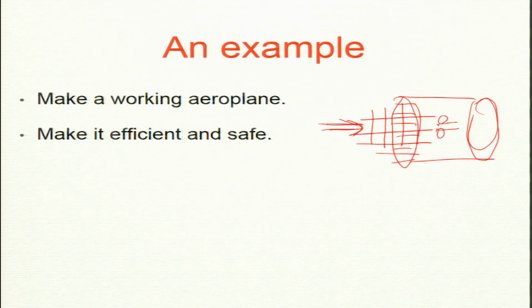You put a small aeroplane. You can't put a big aeroplane. Then we can make measurements on this aeroplane. You can measure the stresses on the wings, how much lift there is on the wing. All these experiments are done with small aeroplanes, and there is an interesting property of the Navier-Stokes equation. If you can measure the forces on this small plane, then you can extrapolate for the same Reynolds number to a large aeroplane.